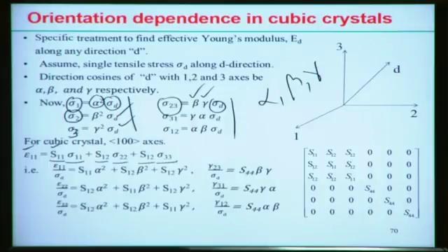That system of equations comes from the matrix notation when using the compliance terms for the cubic crystal structure. Here we see that in that matrix there is S11, S12 and S12, and the other components are 0. So from here we can directly find the relation of strain and stress in terms of the compliance terms.